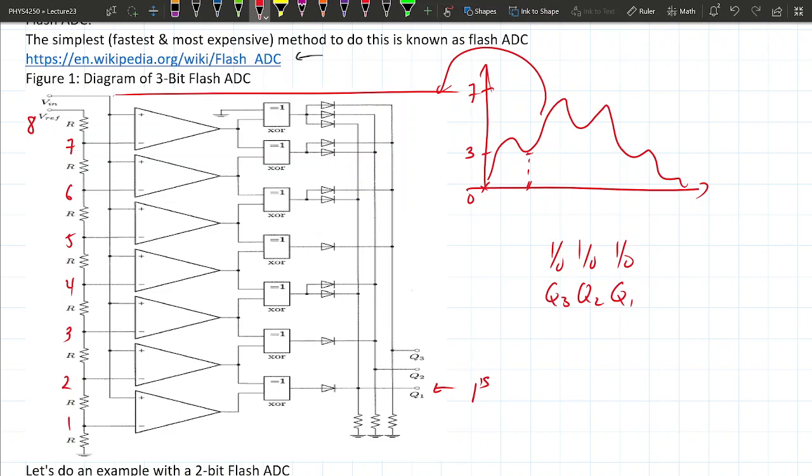But up here, this is also connected to another exclusive OR gate. This output here is still 1, but the one above it is 0. So this is exclusive OR between 0 and 1. So that pulses an output of what? High or low?